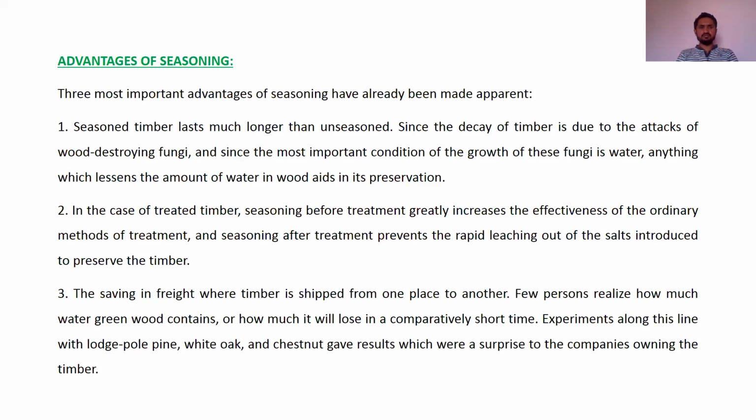So here, when you have brought fresh timber, at the beginning, before the treatment, the seasoning starts in a natural way, and it runs in an effective way. As the moisture content in the timber starts to reduce to a certain extent, the seasoning speed will reduce. At the starting, suppose the moisture content in the timber is around 50%.